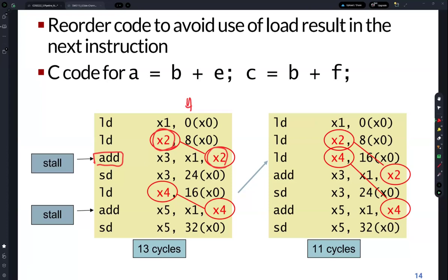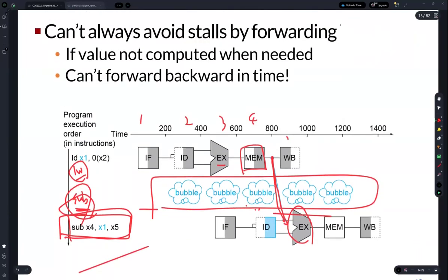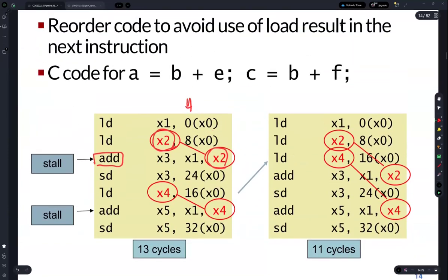And what's the problem? The problem is that the add instruction needs to receive data from the former load instruction. But we learned that if the former instruction is a load instruction and the very next instruction requires the data from the load instruction, then the processor needs to waste one clock cycle, right? So we can observe the pipeline stall.